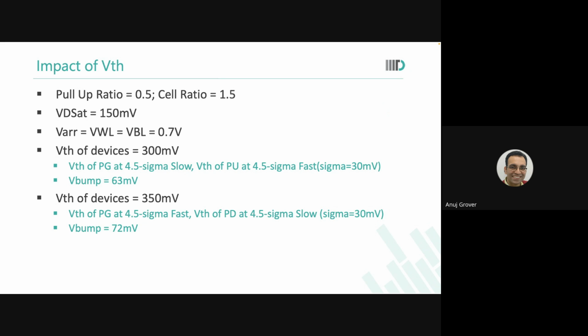So DTCO, Design Technology Co-Optimization, is a term that you will hear very, very often if you go into either standard cell design or analog circuit design. Basically, if you go into full custom design, whether towards standard cell, memory, or analog, DTCO is something that you will hear very, very often in the advanced technologies. In older technologies, technology and design would work in silos. But today they can no longer work in silos. They have to learn how to work together. They have to learn each other's language.